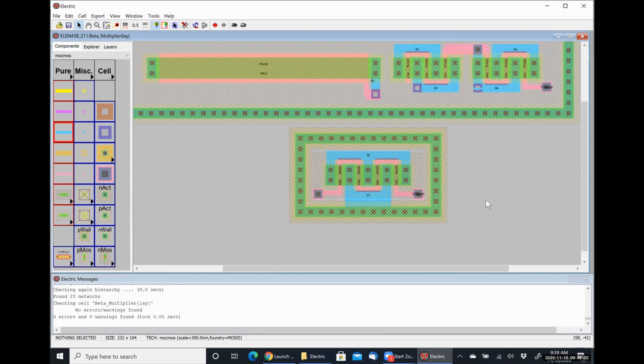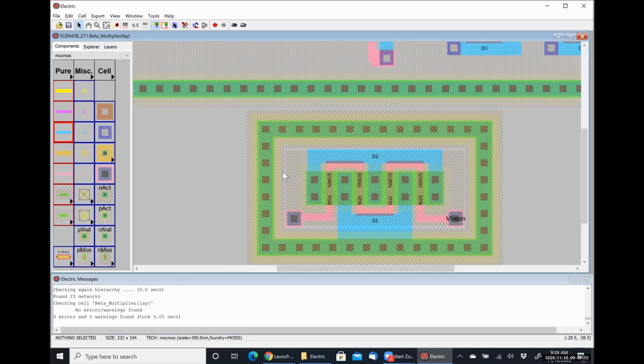So do we not need an N-well region to cover up the little gaps because it's not giving us an error, or is it necessary, I guess is the question. So for this, it's actually a P-well region. And the reason why it's not giving us an error like it does when we do the N-well region is because the substrate is also a P-well region. So we could put one in there.